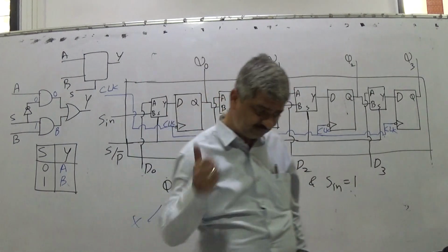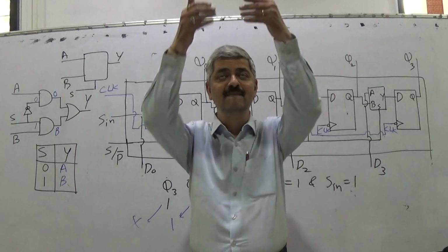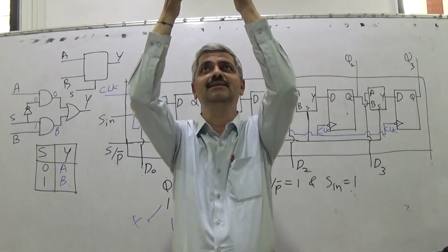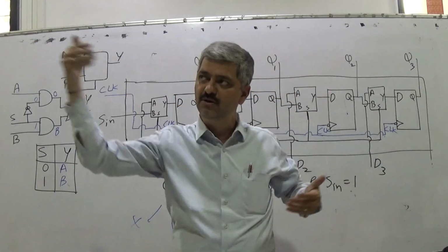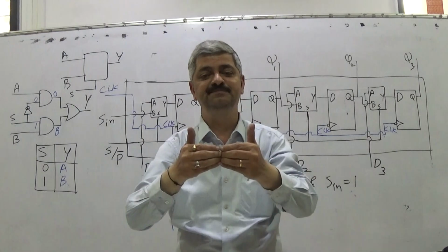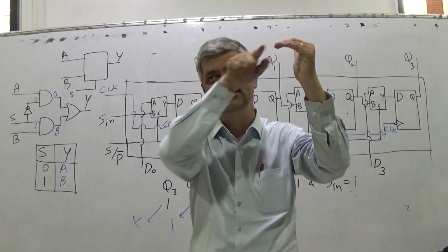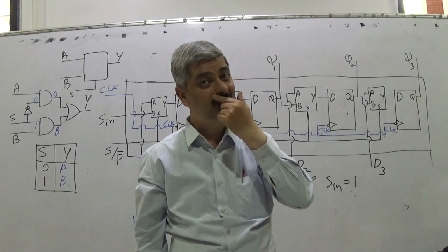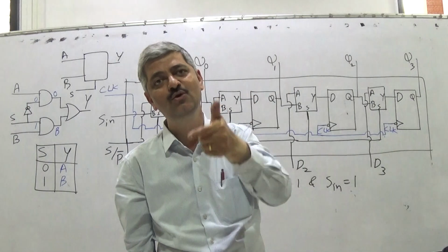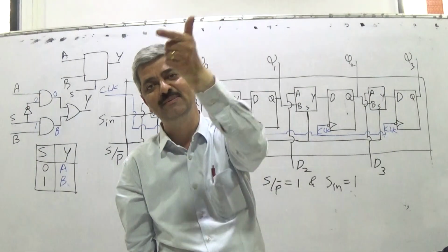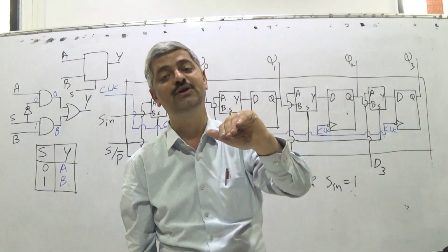So right now, for shift register, I will ask a very interesting question. So what does a shift register do? Shift register can parallelly load the data. You can put the data, that data is loaded parallelly at the output. So all 4 bits are put on D's, those appear on Q's. Or you can put the data one by one. So old data you can shift, new data you can add. From where you can add? So old Q0 becomes new Q1, old Q1 becomes new Q2, old Q2 becomes new Q3, and old Q3 goes out. And Sin becomes new Q0.